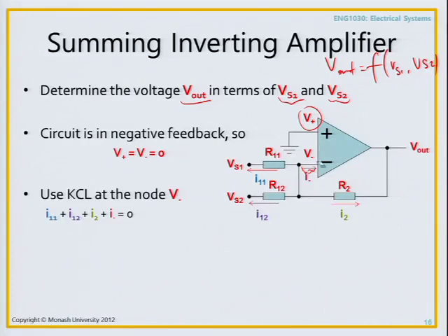Next, same method. Use Kirchhoff's current law at a relevant node. So which node do we use, I would hear you ask? Well, the choice of node you will get better at picking once you've done a few more examples. In this case, there's only one real node which has multiple directions. That's usually a good node to pick. You'll start seeing op amps which have lots and lots of nodes and lots of directions. Picking exactly which node to do KCL on is a bit of an art which you'll get better at by practice, like anything.